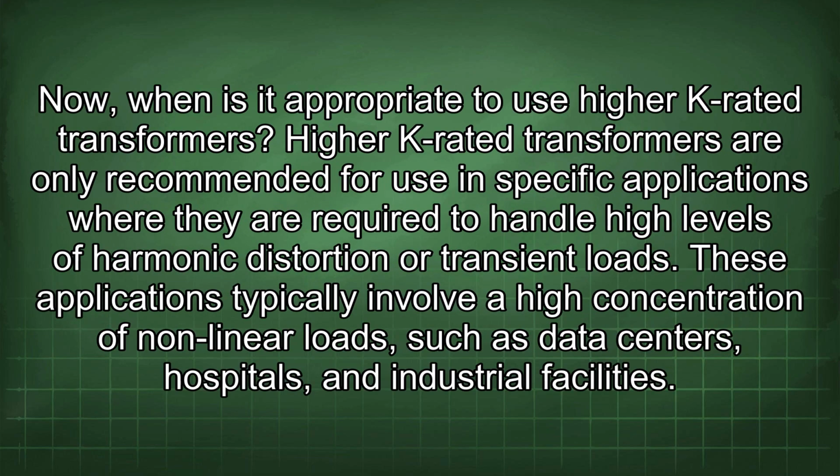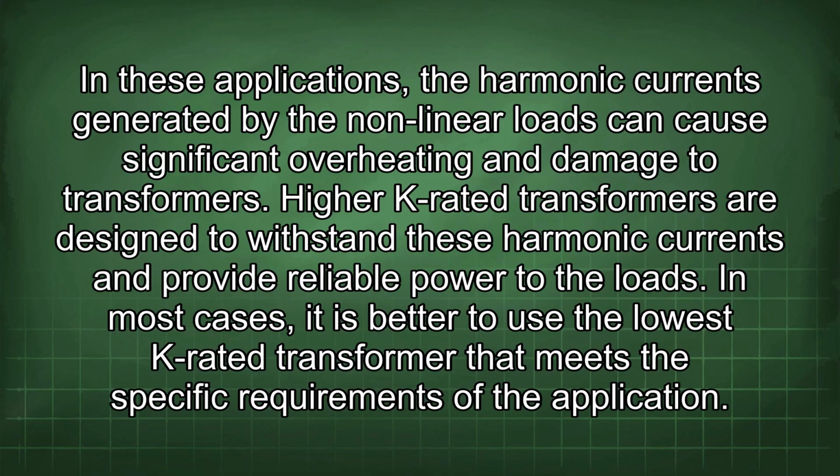Now, when is it appropriate to use higher K-rated transformers? Higher K-rated transformers are only recommended for use in specific applications where they are required to handle high levels of harmonic distortion or transient loads. These applications typically involve a high concentration of nonlinear loads, such as data centers, hospitals, and industrial facilities. In these applications, the harmonic currents generated by the nonlinear loads can cause significant overheating and damage to transformers. Higher K-rated transformers are designed to withstand these harmonic currents and provide reliable power to the loads.